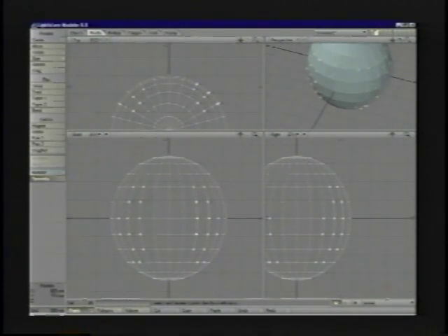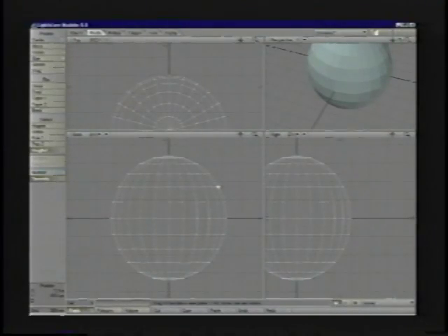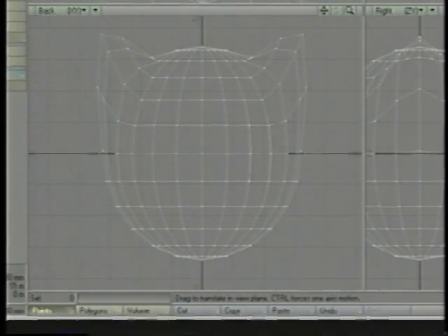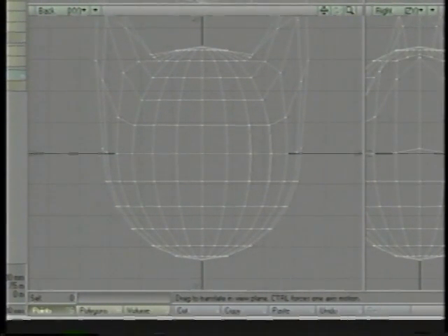And so I've got these, let's just do a dragnet on one of these points here. So I'll select dragnet. You can see symmetry stays selected. And I'm just going to select one of these points and start to pull it out. And you'll notice that the points on the other side are doing exactly the same thing that the points on the side that I clicked on are doing. And so this is kind of cool, especially if you're making characters or faces.